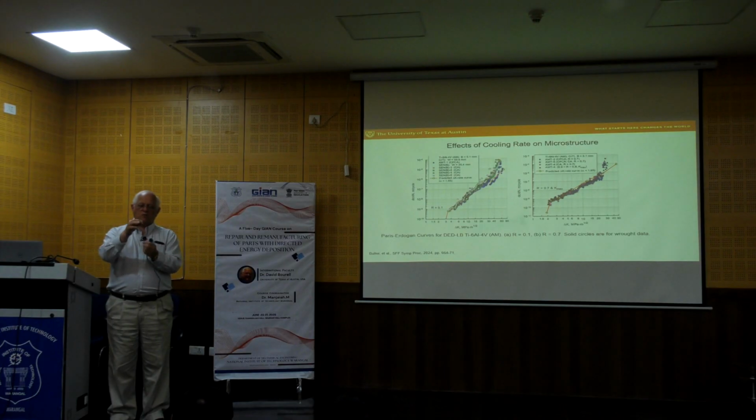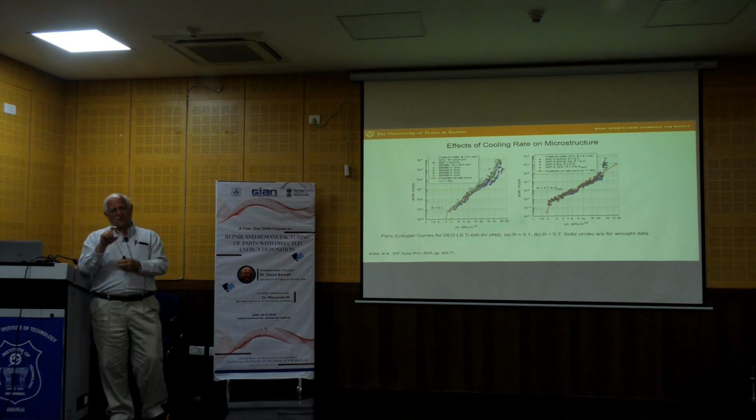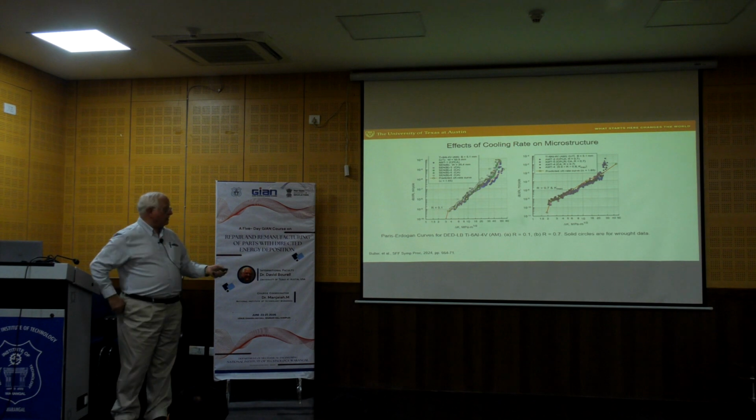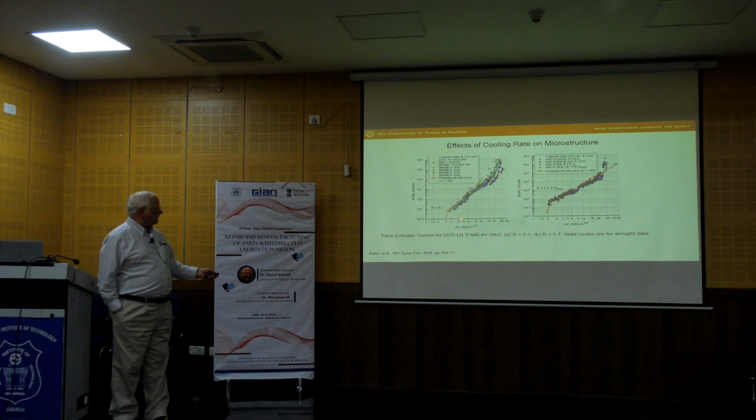As I cycle up in tension, I'm increasing the stress level, which increases the stress intensity factor. And then when I go to the low end of the cycle, the stress intensity factor drops. And what I do is measure that difference, which becomes delta K.